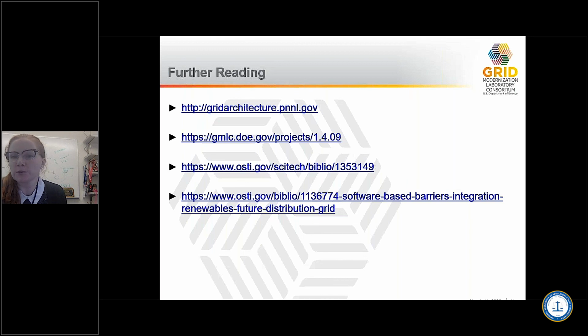The answer to everything is always it depends. It depends on what type of fault it is. It depends on the issue that's happening. It depends also on the layer of analytics that you put on top of all this. I think a lot of the times when we answer questions on smart meters, we'll say it depends. If they're reporting fast and if they're reporting set types of information, yes, they're super useful for finding particular locations. Not necessarily for diagnosing exactly what faulted, but they're fairly good at diagnosing that something has faulted, if that makes sense.